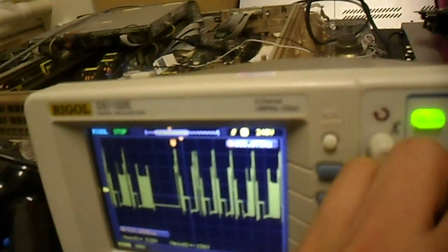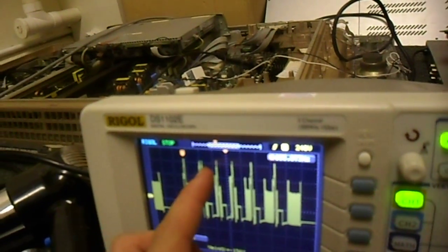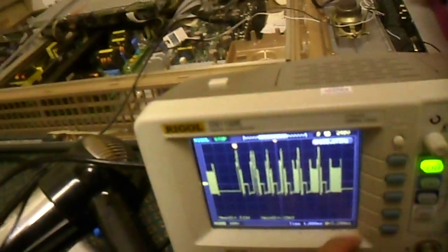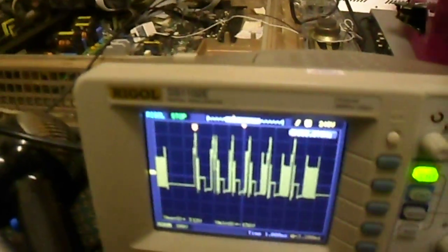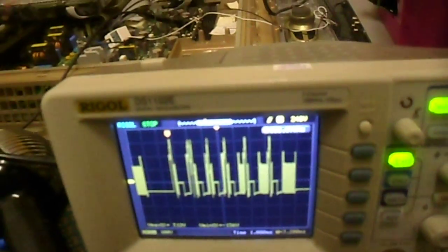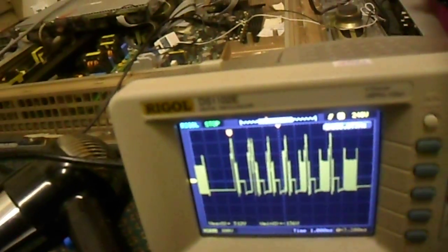So there's a very long one, and then the cycle repeats. And basically, how many reset periods have they got? You've got 1, 2, 3, 4, 5, 6, 7 reset periods. So it's a 7-bit driven plasma panel, whereas Panasonic nowadays is using 10-bit driven, but they only update the screen 60 times a second. So you get a 600 Hz subfield drive, which is not the same as a 600 Hz LCD. It's the same as a 60 Hz LCD, but it will have motion performance much better than any LCD, because each sustain period basically lights up the panel instantly.